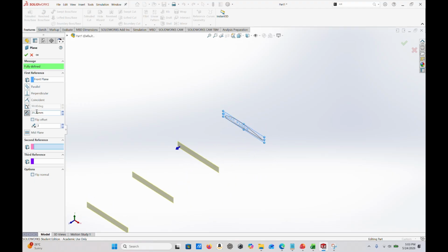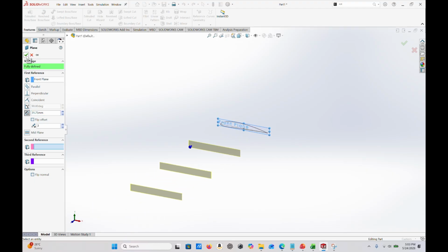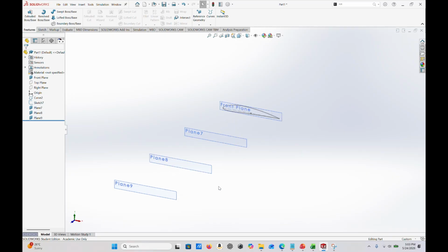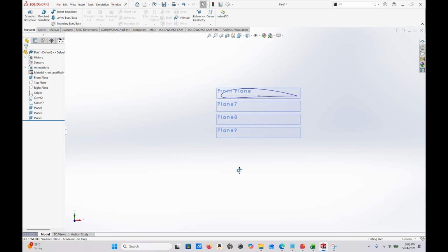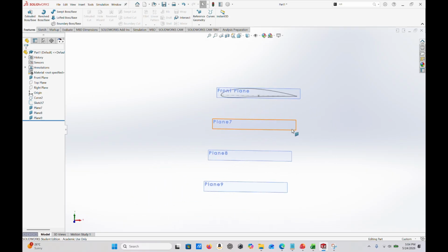And you want to make sure that the value is set on 31.75 millimeters. So that's 1/3 of the previous value that we set on the previous video, so we can have 3 consecutive planes. You can see those planes shown here, and we're gonna have to copy all the airfoil onto each of these planes, and we're gonna change the twist angle at each plane.